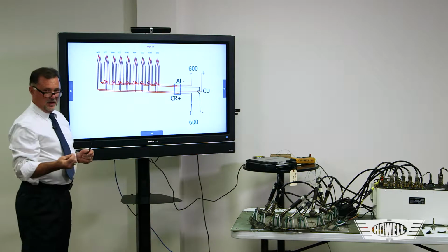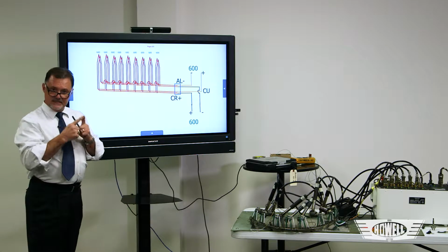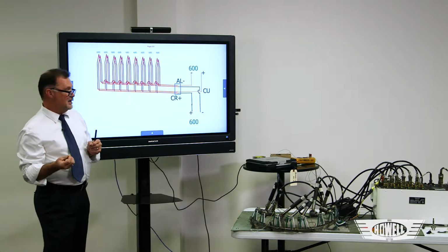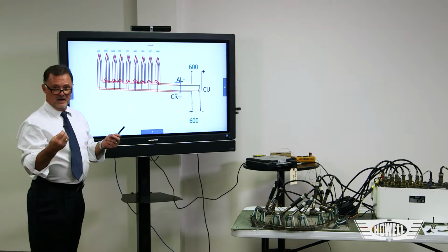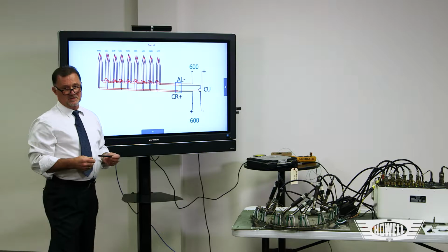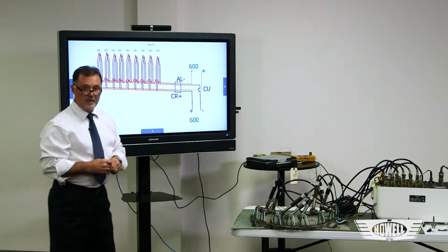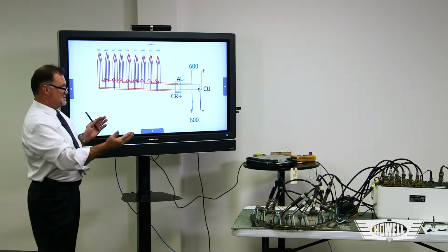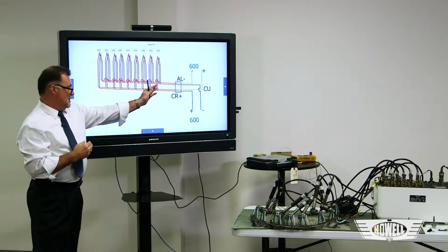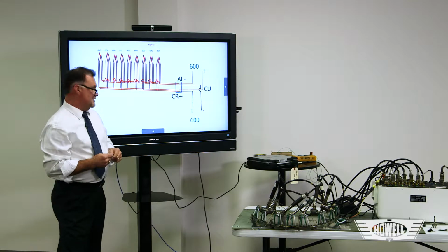This is an isothermic block, and when you're working with thermocouples, you always have to be careful that if you introduce dissimilar metals, you could potentially be creating a thermocouple which would affect all of the overall averages. So they'll have what they call an iso block. The law of intermediate metals states that you can introduce other metals, such as copper, provided there is not a temperature differential at that connection and where it's being read at. So these iso blocks are used to create that environment.